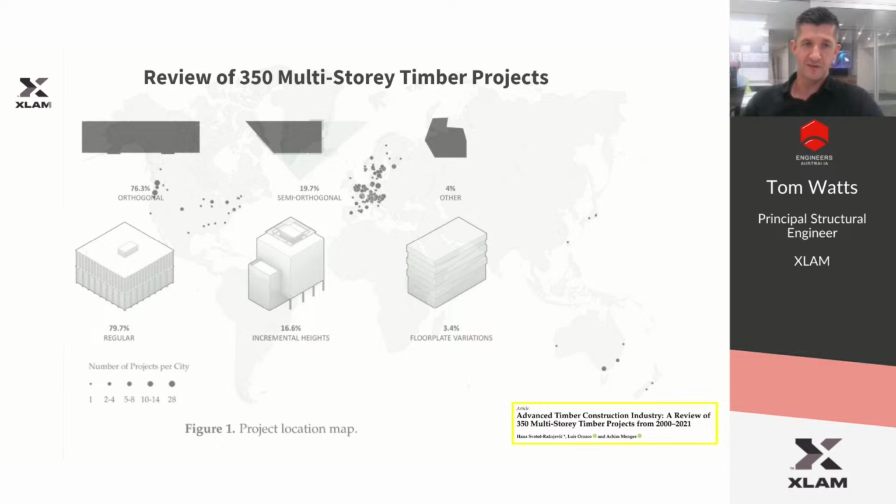What stands out as being really common to a lot of these projects, and certainly what we see as being key to being efficient in mass timber projects, is the orthogonality. By far and away, most of the projects are fairly rectangular, boxy buildings without too many steps in the floor plate. This keeps the uniformity and simplicity of detailing key, which is an important part of making the projects economical, and avoiding things like load transfers and complex structural systems that add to the cost of the system and can make timber projects prohibitive in some cases. You can also see that the vast majority of projects were carried out using a combination of materials. Pure timber projects only made up 22% of the projects, so there's still a majority component of concrete and steel being brought into these projects.